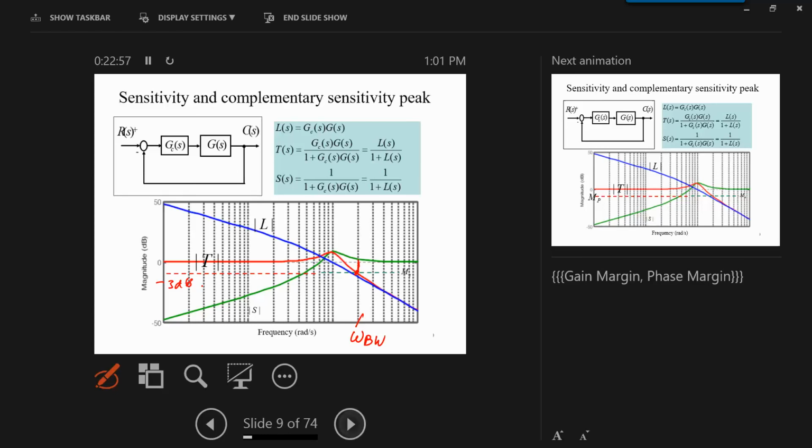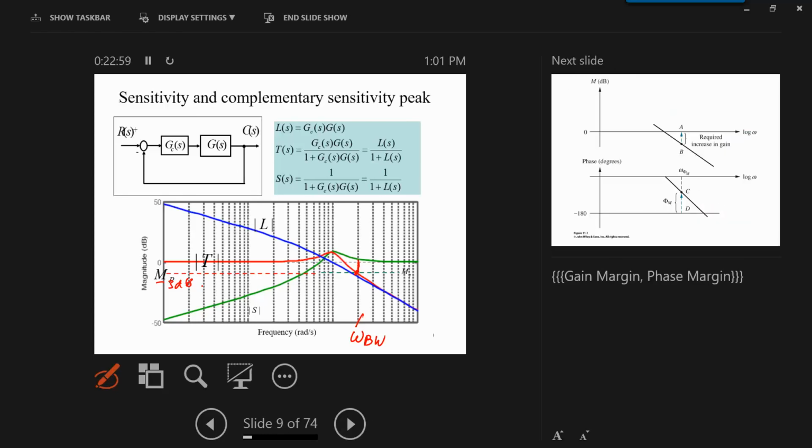Yes. So regarding the last curve, as the frequency goes to 0, that's for the error function? As you go here, the magnitude will go even smaller in dBs, right? Minus 50, minus 60, whatever. So as omega goes to 0, in this direction, this will go to minus infinity.